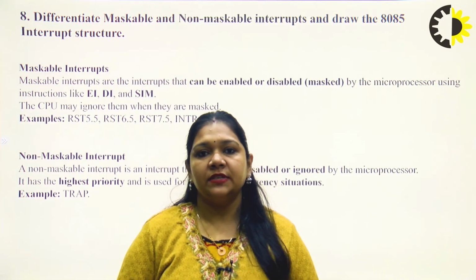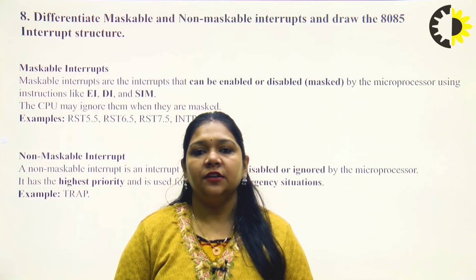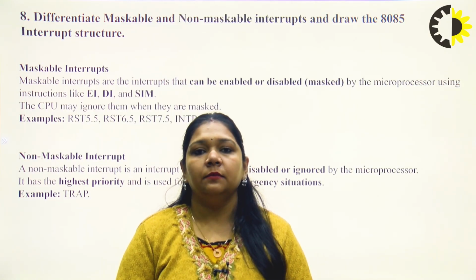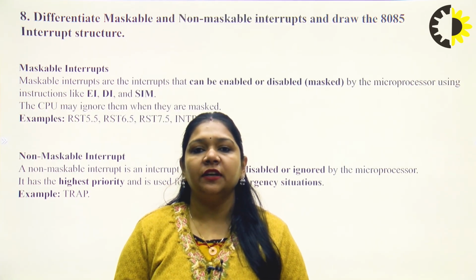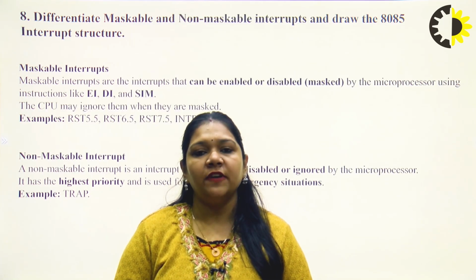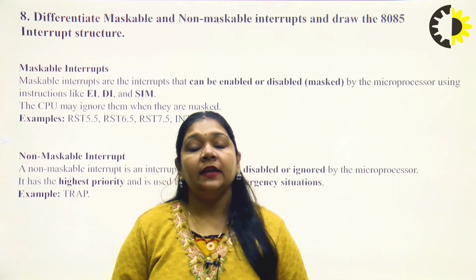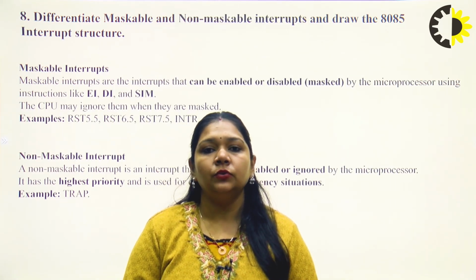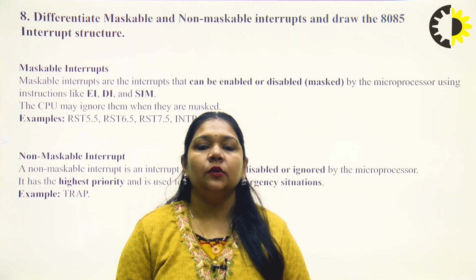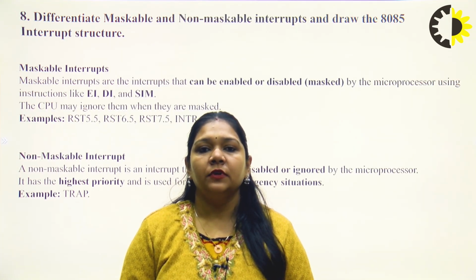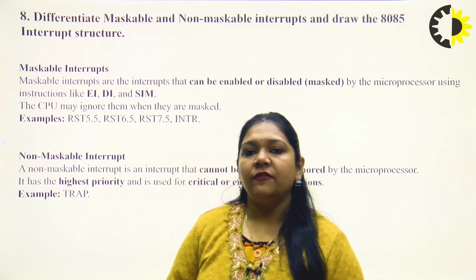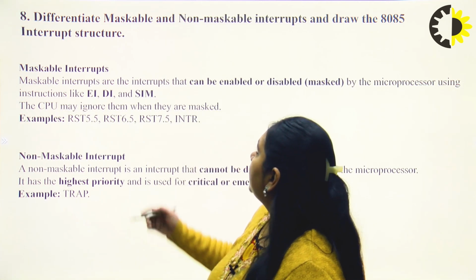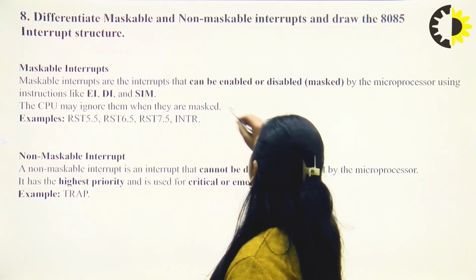As the name suggests, maskable interrupt is an interrupt to which you can put a mask, and stop that interrupt from interfering in the main program of the 8085 microprocessor. In a non-maskable interrupt, you cannot mask that particular interrupt, and you have to service that interrupt. So if we have to differentiate between maskable and non-maskable interrupt,